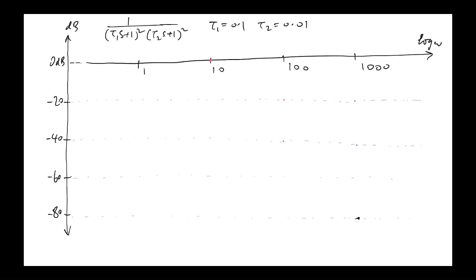Okay, so this is what we're saying T0 needs to look like. And we're going to choose our compensator C to make T have this form. We want it to have this form with these time constants here, because the Bode plot we get will be such that the magnitude of this is 1 almost all the way up to 10 radians per second. So it goes beyond what we need. So let's see how we end up with that.